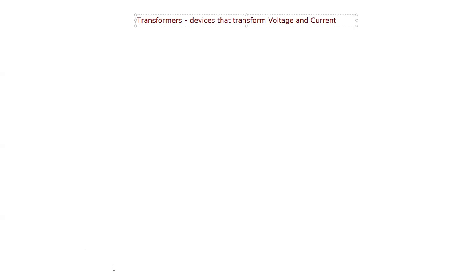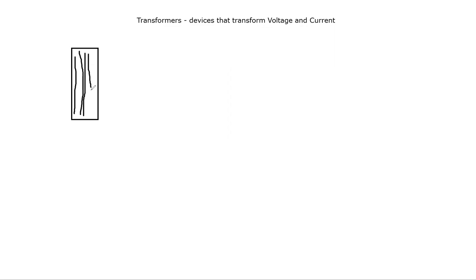So basically you have sheets of metal glued together. Usually it's iron based because you need material that would amplify the magnetic field. So you have multiple sheets of iron glued together with non-conductive glue, right? And they're really thin sheets of metal, so they have high resistance, and you try to avoid all kinds of eddy currents going inside this core.